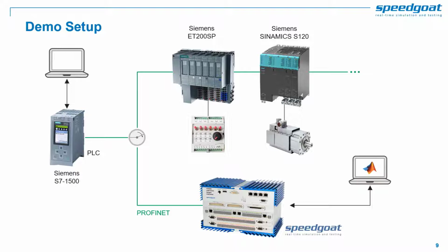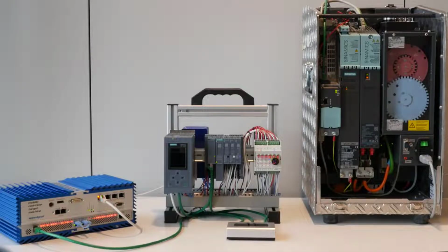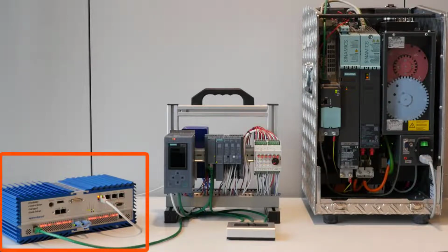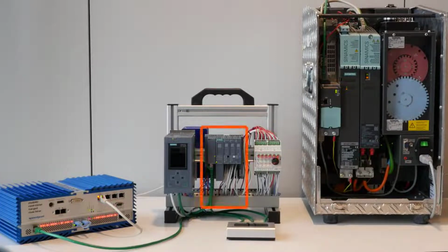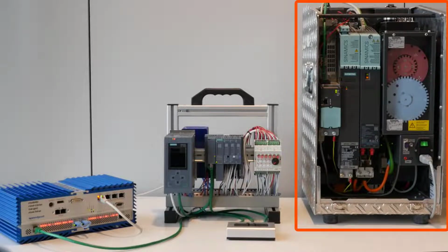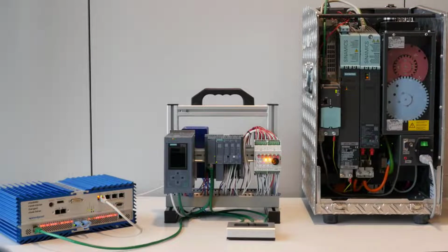Let's go into action. On my desk you see the same gadgets that I have introduced in the last slide. The multi-node simulator, the PLC, the I/O coupler, the switch box, and finally the drive controlling two motors. In a factory, the blue motor could drive a conveyor belt, for example, transporting bottles, and the red one moving a filling needle, filling the bottles.